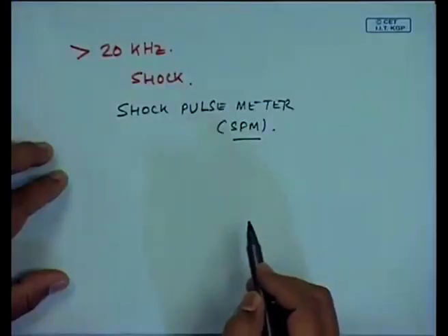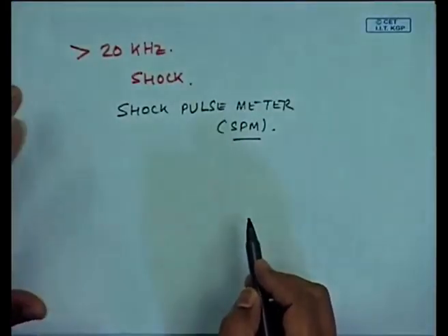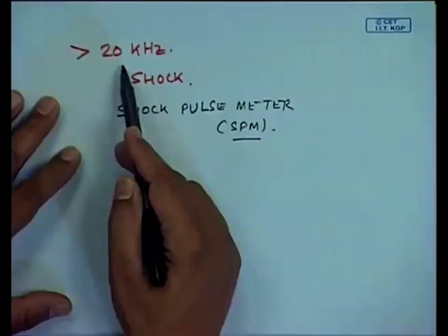It is not the normal operating functions of a bearing, but it is if there is a defect like a pit, like a defect in the inner race, outer race. Because of this pit I am getting an impulse and this impulse's frequency response is a wideband response which has excited the right hand side of that equation. So, I am getting large motions at the resonant frequencies of this bearing, and as a bearing designer they always make sure that the bearing's natural frequencies are not in the operating frequencies of the bearing and they are at frequencies much higher than the operating zone and usually of the order of 20 kilohertz.